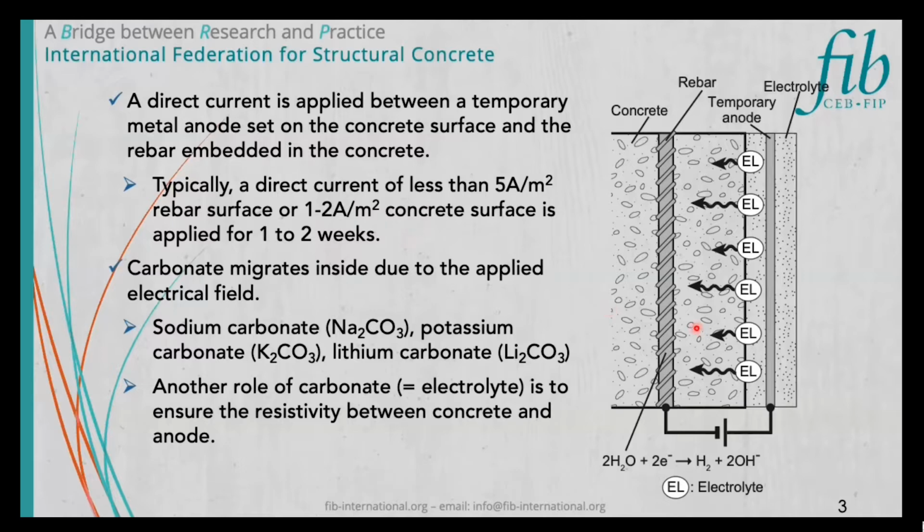Carbonate in the electrolyte supplied on the concrete surface migrates inside by electrophoresis. Generally, sodium carbonate, potassium carbonate, or lithium carbonate is used here. Another role of electrolytes is to ensure the conductivity between concrete and the anode to make the migration easier.